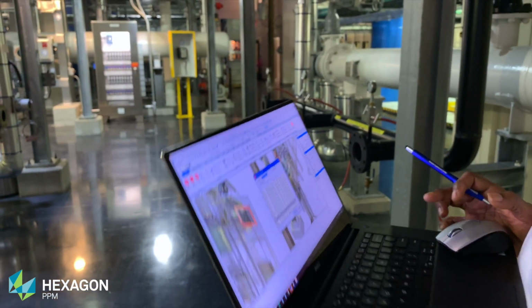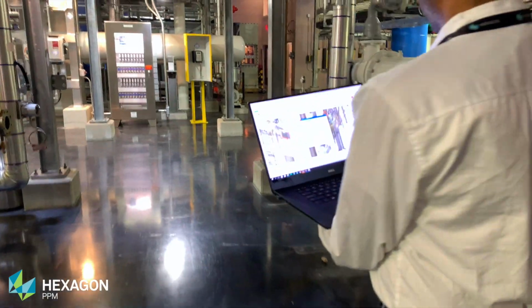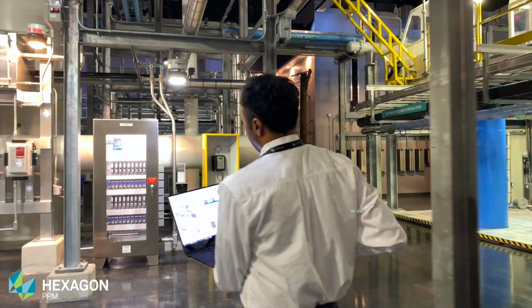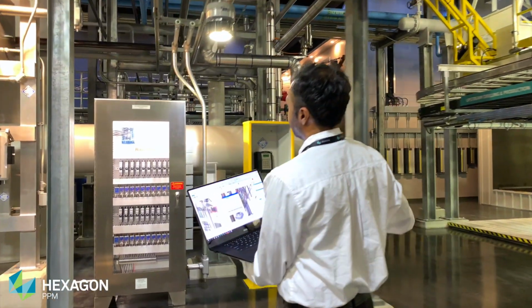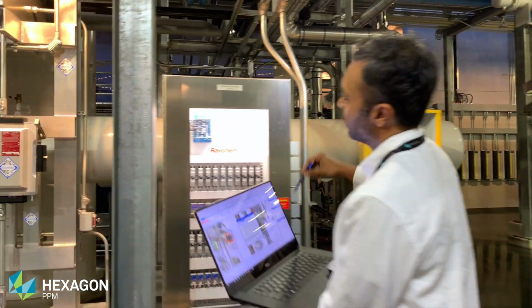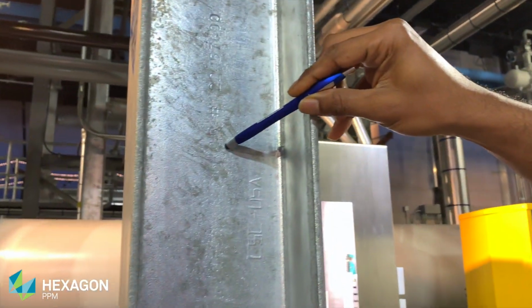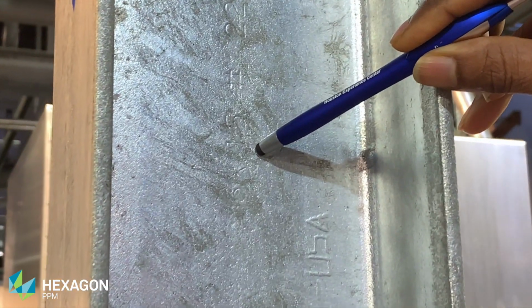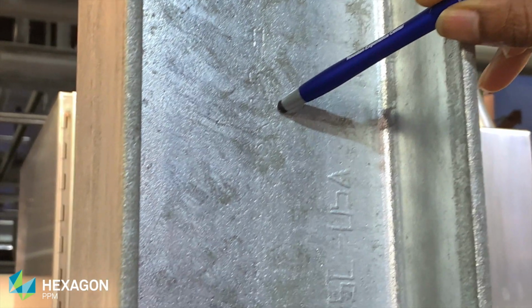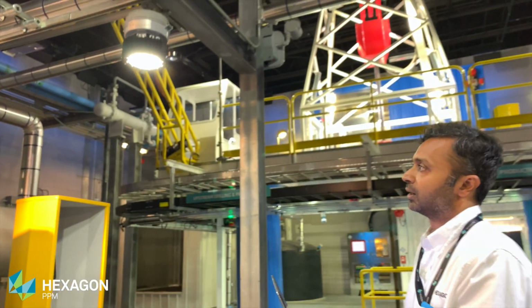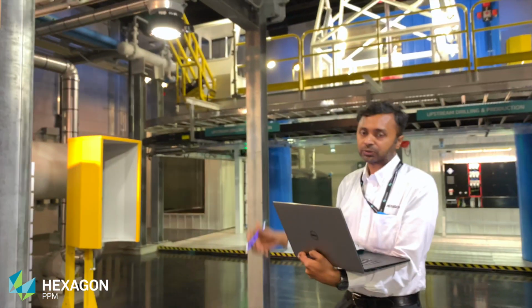Okay, so let's verify that. Here is rack frame number 1, 2, and I'll take you to a lighted area where you can actually see the shape of this column. You can see it's about 6 by 15. Let me zoom into that. Yep, there it is, 6 by 15, right? Yep, so it matches. So I don't have to climb up on this rack to take measurements.